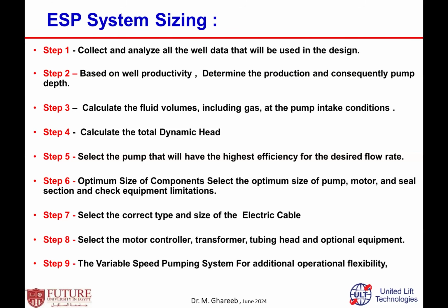I collect and analyze the data: will it be stable with time or is it expected to change? What is expected to change? Based on the well productivity, I have to determine the production rate and the pump depth, and after that the fluid volume, including gas, at the pump. Remember, the fluid volume at the pump is different from the flow rate at the tank. You have to consider the shrinkage factors here.